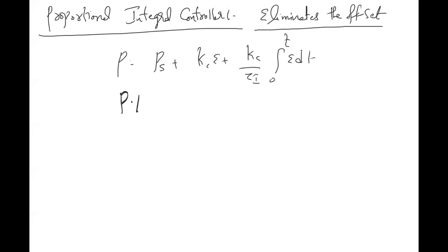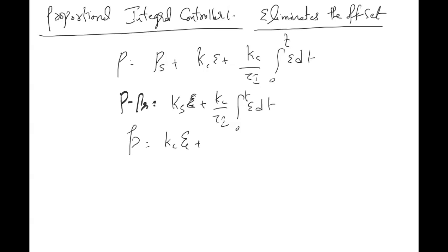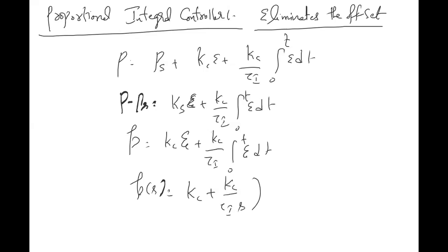So what is the transfer function? P minus Ps equals Kc into E plus Kc by tau I into the integral of E dt. So what is the transfer function?